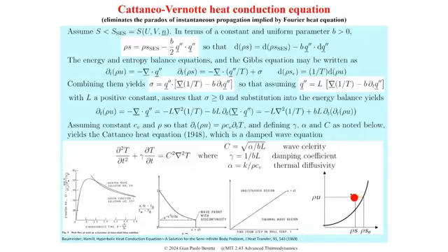So assigning it the equilibrium entropy introduces an error, and it's interesting to see how you solve that problem by assigning to the fluid element or continuum element not the equilibrium entropy, but an entropy which is less than equilibrium, and departs from equilibrium more the higher the heat transfer.